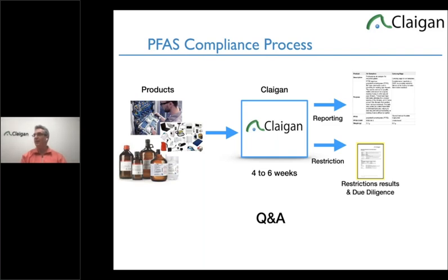Can you walk through a PTFE part? Does it contain PFAS? PTFE is a PFAS. It's a perfluoro polymer, and you have to report. It's intentionally there. It's PTFE. You have to report it, but it's not a restricted one. That's PFOA and longer. It's a very specific non-polymer one. So the PTFE is the material. It's what's reportable. It could have PFOA in it, which is not reportable, but it is restricted. It doesn't have to. You can make that PTFE just fine without PFOA.